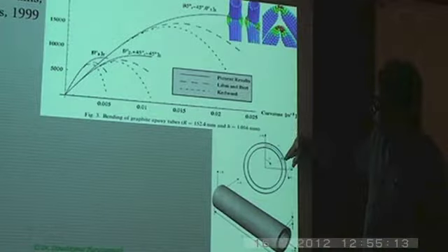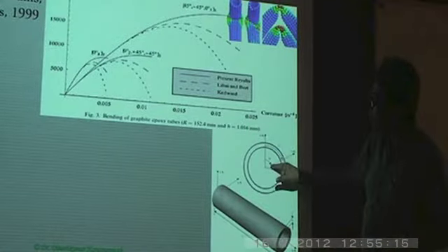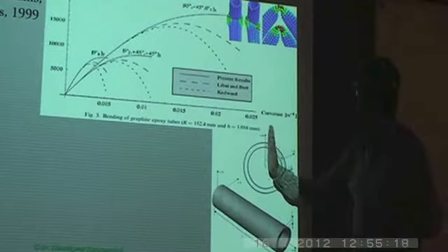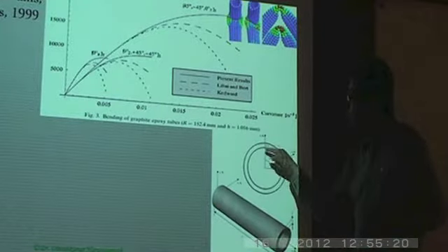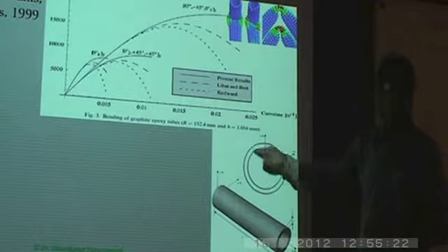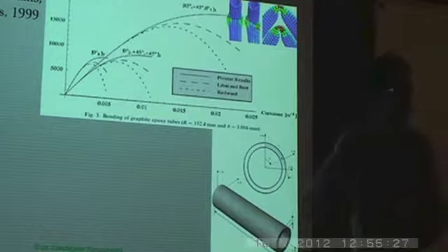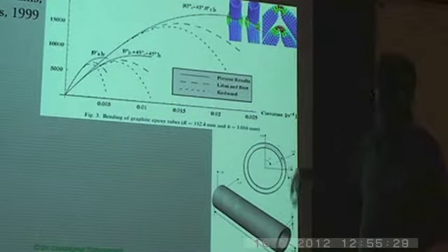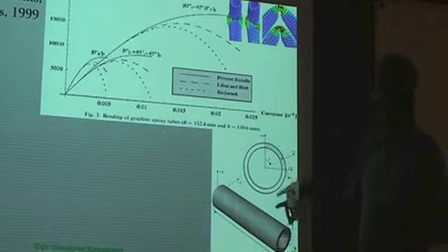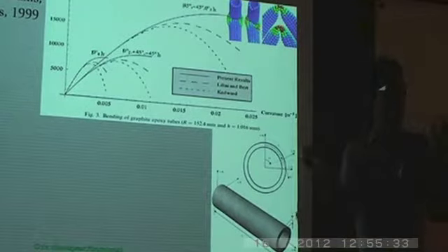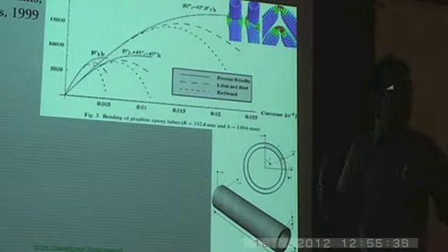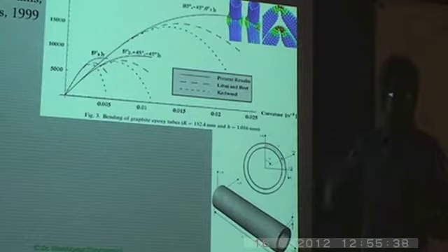So then if you express in terms of that, and theta at some location, let's say theta is 0, and then you basically talk about theta varying from 0 to 360 degrees. If you express in this set of coordinates, typically the derivation becomes much simpler, taking advantage of the axis symmetry in the geometry. Of course, the loading itself is a bending load, which is not axis symmetric loading. So the advantage is not throughout the derivation, but at least parts of the derivation get simpler if you use a coordinate system basically like this.